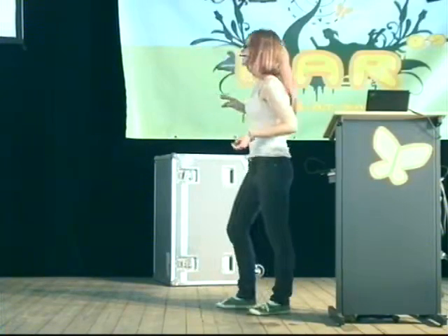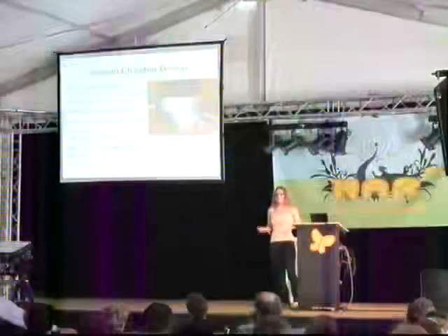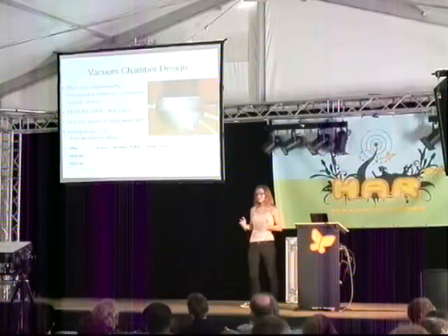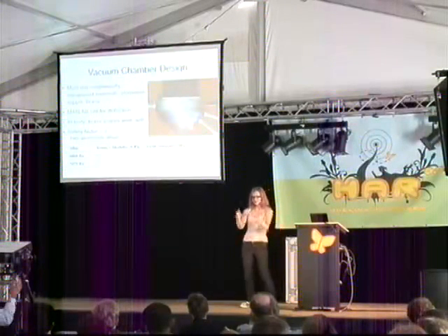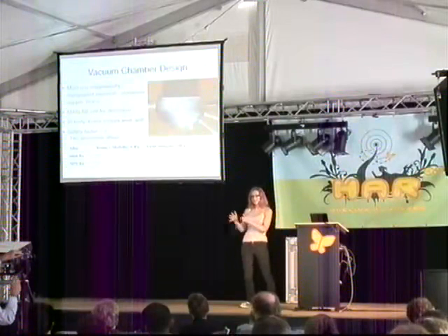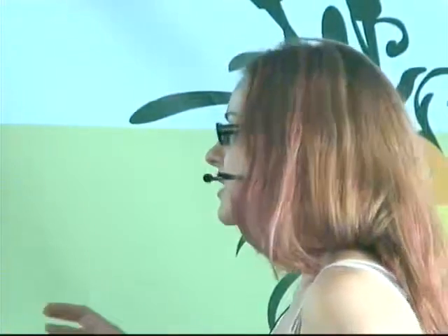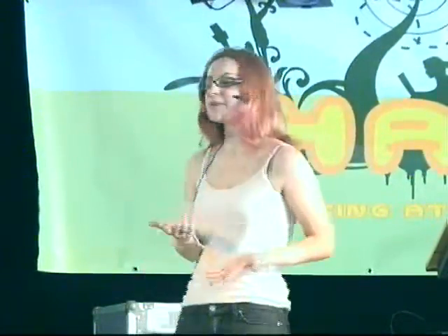Now, two types of aluminum that are good to be aware of. I'm not sure how much people know about these types of aluminum, but 6061 is the cheapest type of aluminum. It's standard, it's very easy to machine. I use this for the body of the cyclotron because that can have thicker walls, so it's not under as significant stress. Top and bottom lids, it's better to use aircraft grade aluminum, 7075. That's really, really annoying to machine, but you can make it smaller, so you'll be able to fit the cyclotron inside a tighter gap, which is useful depending on the type of magnet you're able to buy or make.